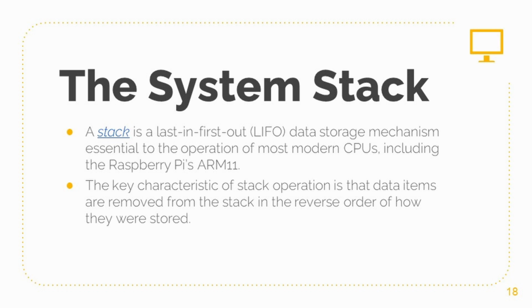Subroutine calls. Similarly, when a subroutine or interrupt handler is invoked, its context, including registers and status flags, may be pushed onto the stack. Upon completion, the context is restored by popping the values off the stack. Data storage. The stack can also be used for temporary storage of data, such as intermediate results of computations or parameters passed to functions.